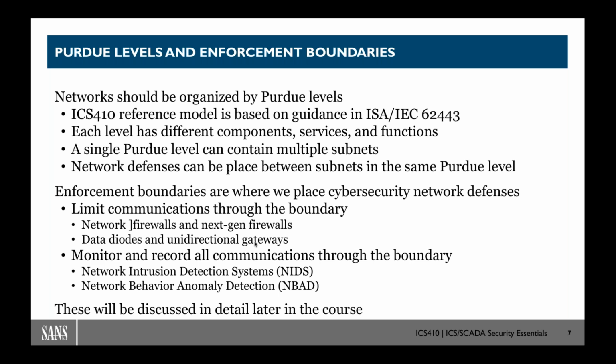environment. Now, on all these diagrams, notice there are many different types of enforcement boundaries mentioned. We're not trying to prescribe what has to be in every single one of those enforcement boundaries, but we are saying that this enforcement boundary is a place where you can do cybersecurity controls. This is where you can monitor. Now the trick is figuring out what types of cybersecurity controls to put in each of those different types of boundaries, because some controls may be very appropriate in one boundary, but not appropriate in another. That's based purely on the technology and the requirements of your control processes themselves.